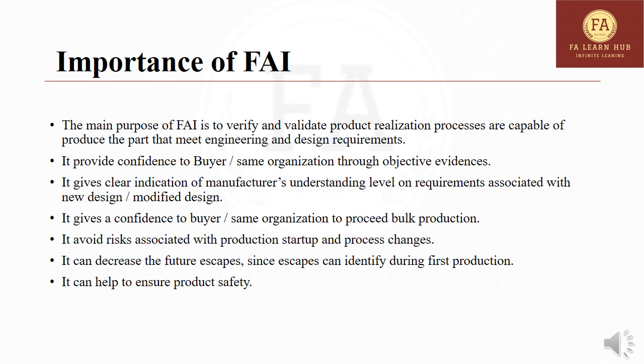RCA was conducted jointly, and the conclusion of the RCA identified that the 250 volts applied on the signal lines affected the signal lines, since the designer had designed these signal lines for a maximum of 100 volts, but the manufacturer applied 250 volts. It induced damage in the signal lines. So here is a clear indication of misunderstanding of the customer requirement.